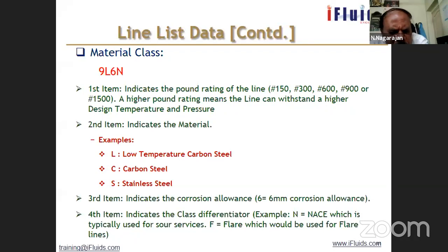What is the meaning? The corrosion department says 6 mm corrosion allowance is required for a plant life of, let us say, 25 years. The meaning is, today you put a pipe with 16 mm thickness into service, and the plant is operating. After 25 years, all the corrosion allowance is supposed to be eaten away. So if you measure the wall thickness of the pipe after 25 years, you will be left with the base thickness, 10 mm. So that is the idea of corrosion allowance.